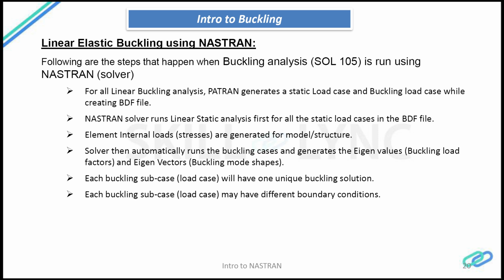And then there will be a buckling load case also. The Nastran solver first runs the static analysis for all the static load cases and computes the element internal loads, and then it automatically picks up the buckling cases and generates the eigenvalues and eigenvectors. So each buckling case within the Nastran BDF file will have the corresponding eigenvalue and eigenvector.